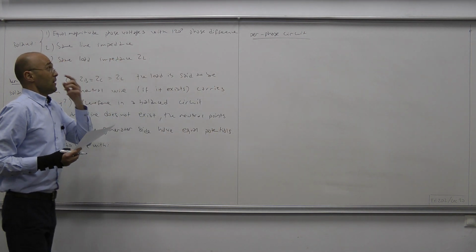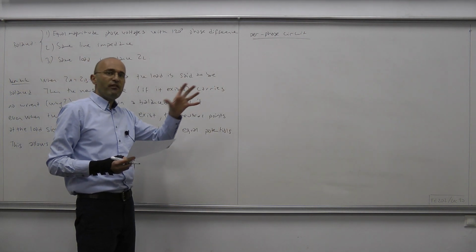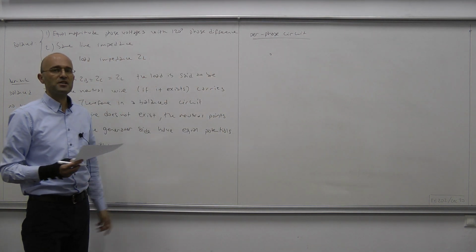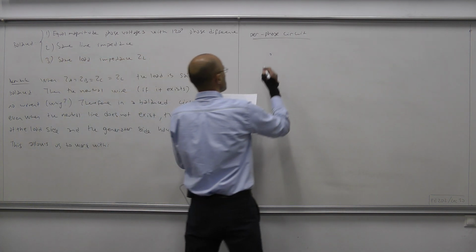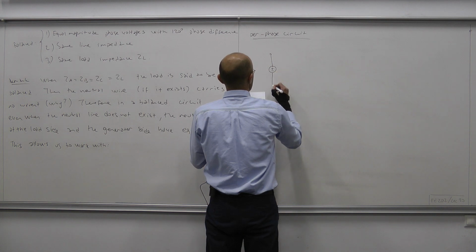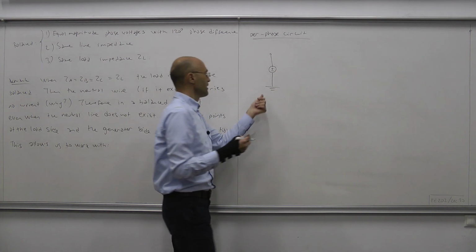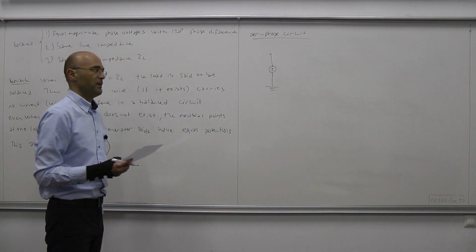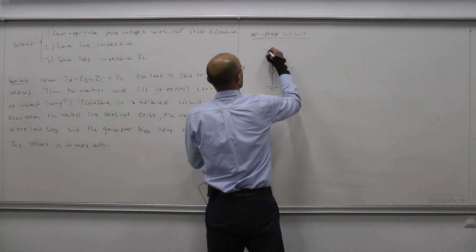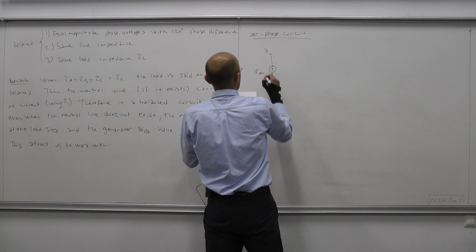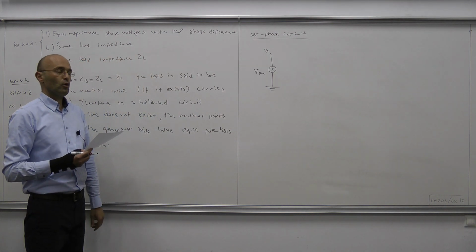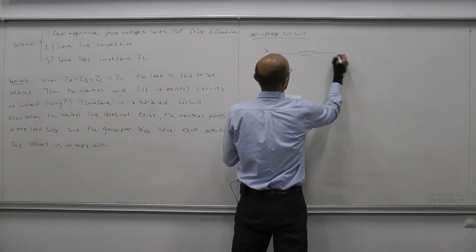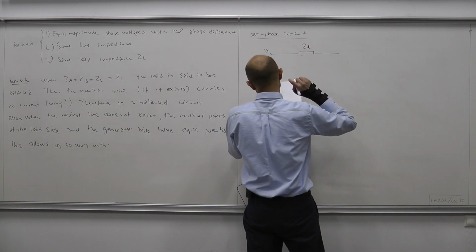Okay. So, thanks to per-phase circuits, we can study each phase separately. And due to symmetry, studying just a single phase will be sufficient. Why is that? Let's see. So this is phase A, let's say. Now this ground node corresponds to our neutral terminal in the Y-to-Y circuit. This node is a. This is our phase A voltage on the source side, and here we have the transmission line with impedance ZL.